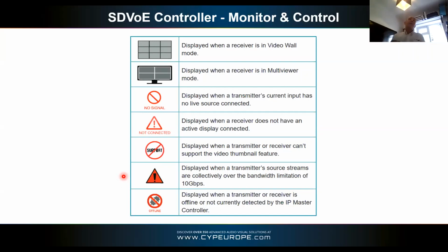This can happen when you've got full 4K 4:4:4 in both your primary stream and your multi-view stream. When you're doing both of those, you can go over the bandwidth, depending on what all the other resolutions are on the multi-view stream and how you're using the rest of the streams for that particular transmitter.